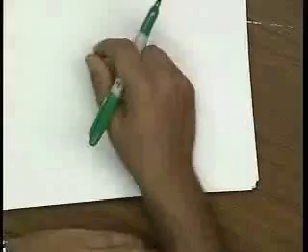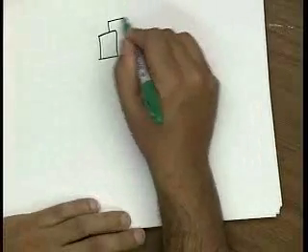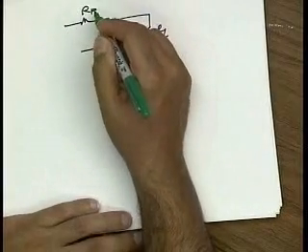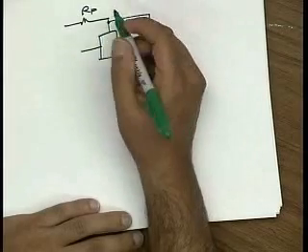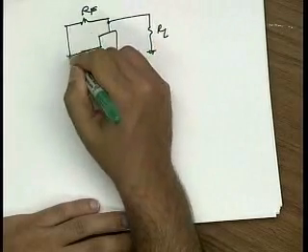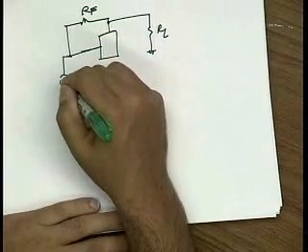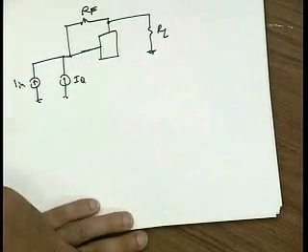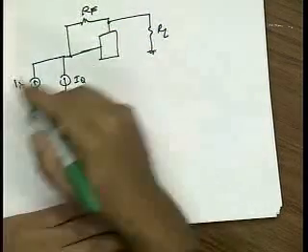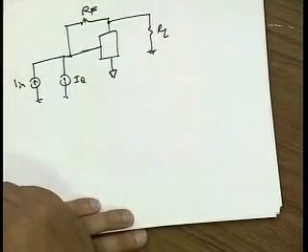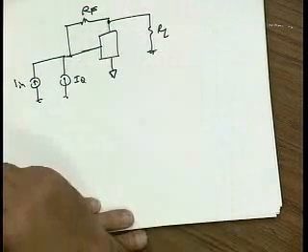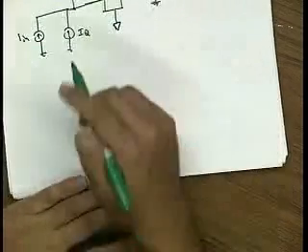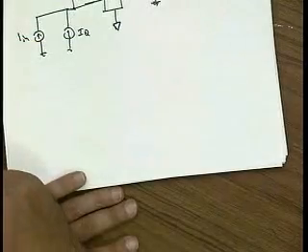All right, then the next part asks you to do the calculation when you have this RF. And you're even told that this is a feedback resistor, so if the word feedback wasn't ringing in your head, there's something wrong with you. If you're clever, though, you would make sure that this is negative feedback, right? So you should first of all verify that this is negative feedback. Okay? And if you verify that the feedback is negative, then you can use the formulas that we derived in class. So all you need to know is the loop gain. To find the loop gain, you need the feedback factor and the forward gain.